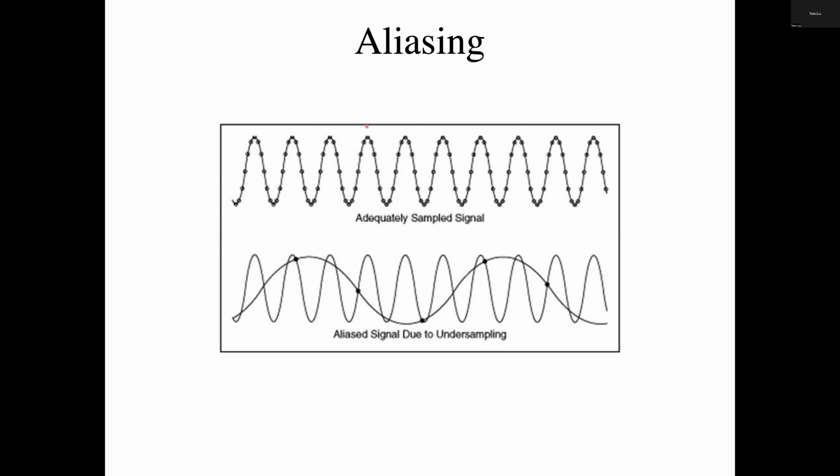If I sample at a rate such that I'm uniformly sampling the peaks here, that will just look like a constant function. So I totally missed it, right? However, if I sample this one, and then this one, and then this one, at least I'll get one up, one down, one up, one down, and it will have the amplitude that's associated with that sine wave, right? So that gives you a sort of visceral best guess as to what the lowest frequency you want to sample is, right?